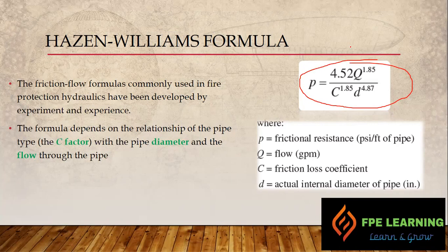The most commonly used is the Hazen-Williams formula, except where we have a problem with antifreeze solutions, chemical additives and so on; then we have to use the Darcy-Weisbach formula.